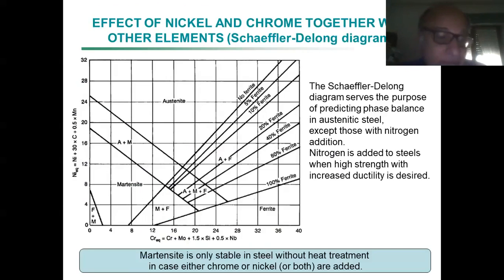I was talking before about liquid nitrogen. Nitrogen enters in a number of situations in steel, and in some cases it's also put in steel to create, for example, some surface layers to better withstand, not only corrosion, but to improve the hardness substantially.